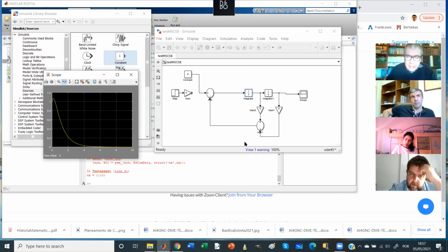I will later tell you what is the mathematical translation of this fact, that you should have your actuators well placed. If your actuators are well placed, by feeding back all the state, you can place the closed loop poles where you want, and not just in certain positions as you get by feeding back the output.